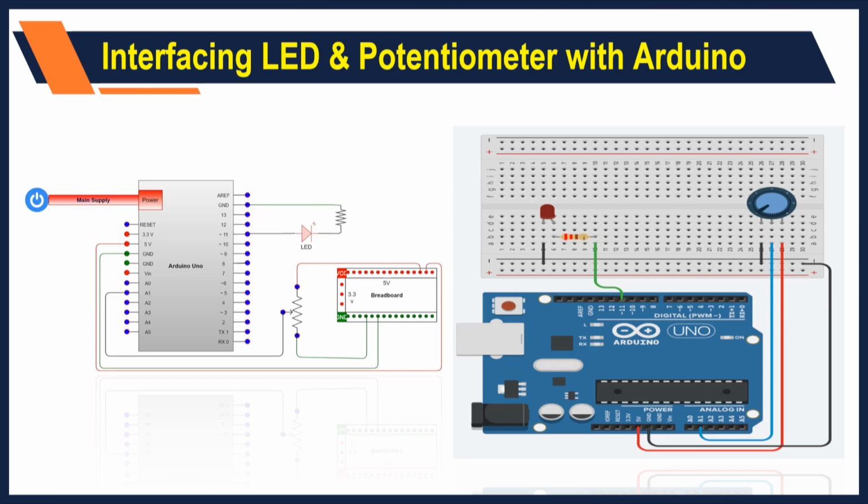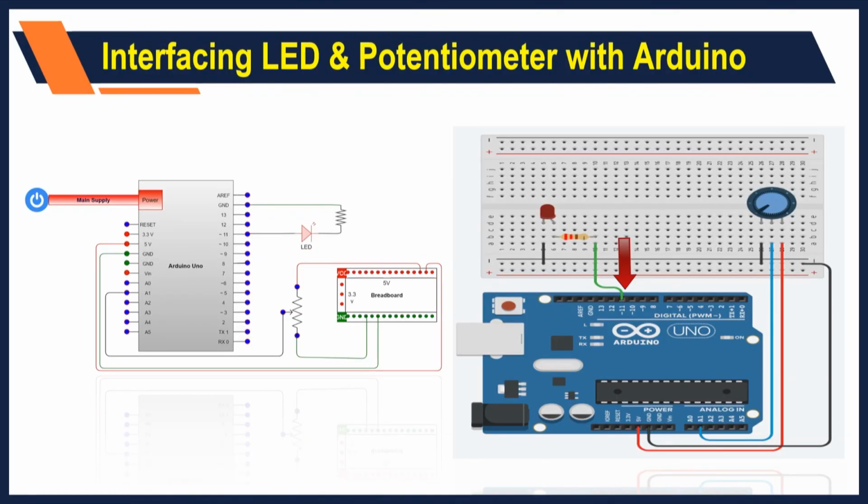The circuit will be pretty simple. First of all, we have a potentiometer. You can see we have connected it on one of the analog terminals. So, depending upon how you need to define it on the hardware side as well as on the software side, you can choose any one of the pins from your analog port. And similarly, the LED I have connected on one of the digital pins over here. The same connection we have to design on the hardware side now.